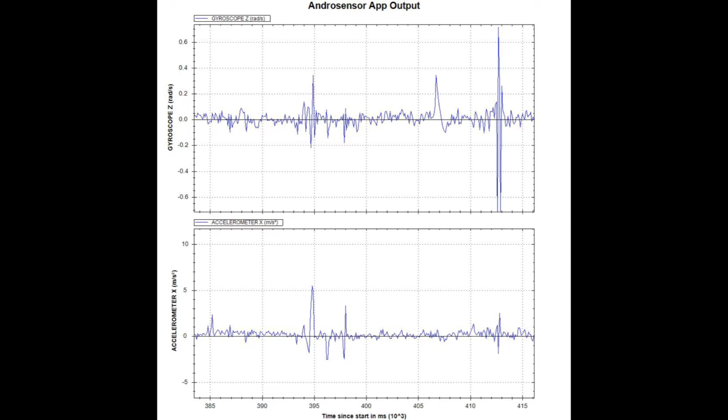These are spikes down on the gyroscope where you can see that the car is moving to the right. You see that in the accelerometer data. You get a few peaks there, probably not as big. The car is probably getting stuck in the middle of the lane, starting around 400 seconds in the dotted lane. And then out at 407, you can see a big spike. That's a pretty wide pulse. You don't see that in the accelerometer data, but that's going in the up direction, so that's going back to the left, so it's probably settling in the lane at that point.